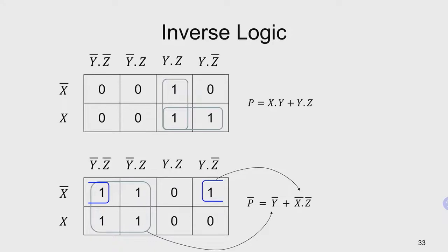Inversing a logic. So if this is our truth table, I'll minimize function p from these two loops, with these 2 prime implicants, it can be written as this. So if you want to work out the inverse of p, then on our truth table, those 0s become 1 and 1s become 0.